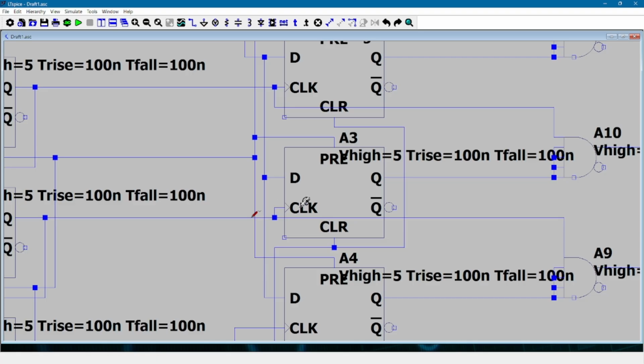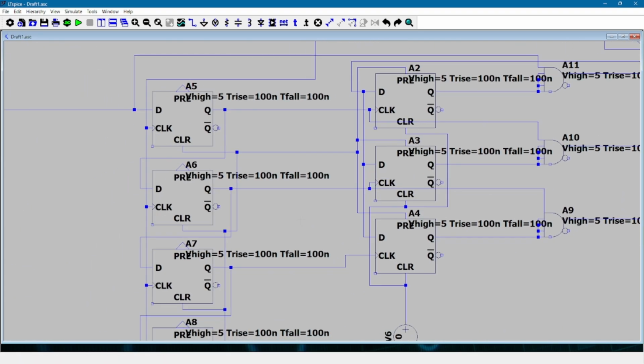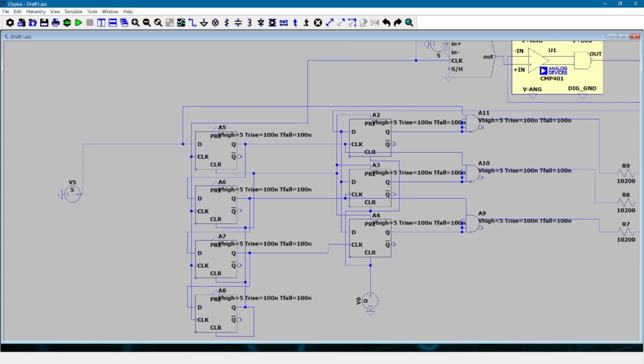If you look here, there's a makeshift shift register. We don't get shift registers on this platform. We only get flip-flops, so I had to make my own. But this shift register thing will be our little clock signal, which will update at 3 distinct times for each of the comparisons.